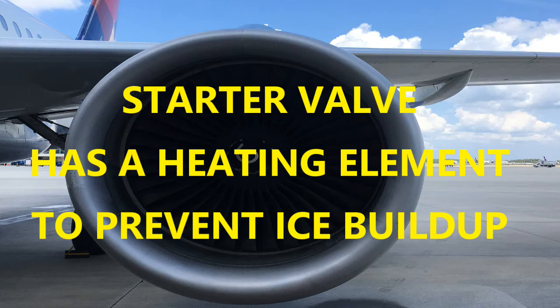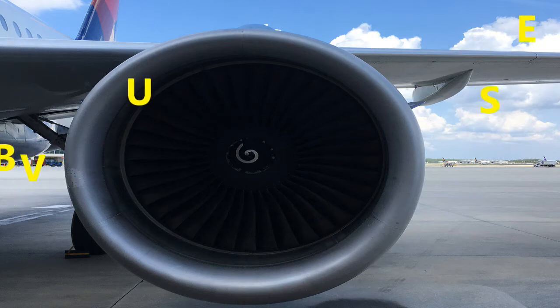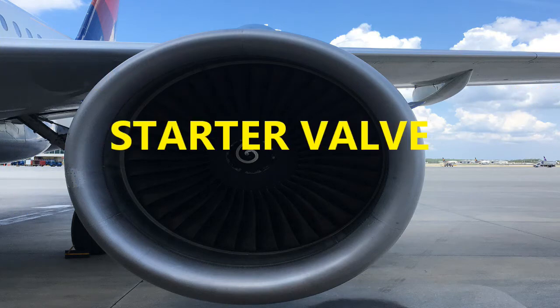Part of the inlet air is going through an orifice and around a solenoid valve, and then it's vented to ambient. So just know part of that is happening with the air coming into the valve. You also have a rotor that's there to provide torque to drive the high pressure rotor through the reduction gear and the clutch assembly that's part of the valve. That motor action is controlled by the control valve. And then there is a manual backup system in case the air starter control valve doesn't work.